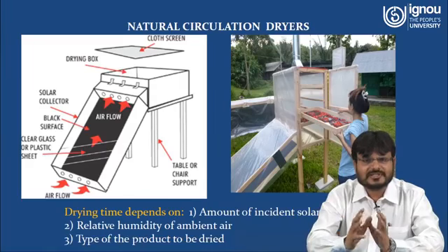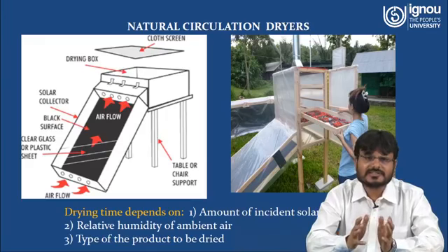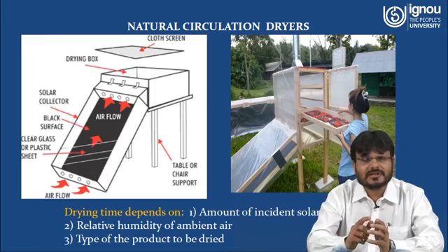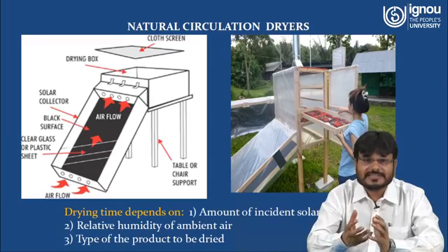Now the temperature is high and air is coming inside the solar collector, and the temperature of that incoming air is the ambient air temperature. Now this ambient air comes in contact with the base of this solar collector. Whatever heat is associated with the absorber will be transferred to the air, so the temperature of the air will increase. Now this air will go, because it is a natural thermosiphon principle, as the temperature increases the air will be lighter.